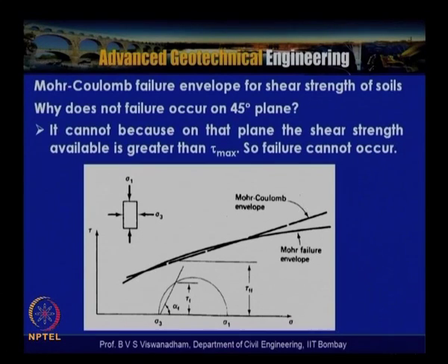So here we have shown a Mohr Coulomb envelope, which is a linear version, whereas the Mohr failure envelope shows the non-linear variation. Now if you have a circle with measured principal stresses sigma 1 and sigma 3, and this is tau f, this circle is regarded as stable, because the vertical ordinate is tau ff, and the shear stress there is only tau f.